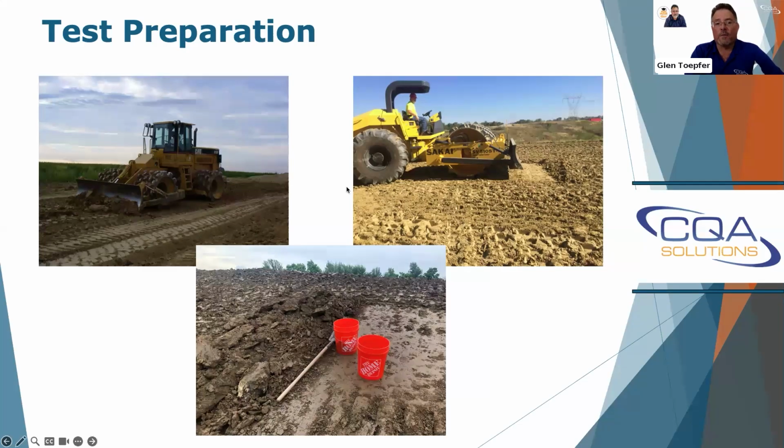That's what they were using on that one project that I told you about, the 2022 project. They were cutting it with a compactor, and one of my suggestions was they cut it with a dozer, and they started getting better test results when they did that and got rid of the voids below the gauge.